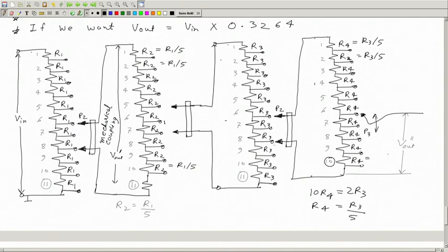So therefore, now how much is the total equivalent resistance of the third stage? We have 11 of them, but these two are in parallel with another equivalent 2. So this 2 and this 2 become only 1. So actually this is equivalent to 10 resistances. Okay, not 11, only 10. And then this 10 resistances, that means 10 R3, is coming in parallel to 2 R2.